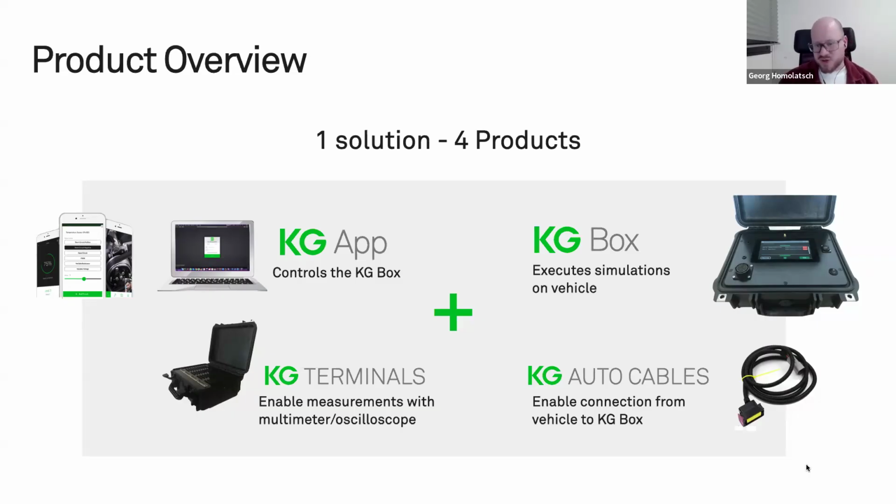That way you don't create any wear and tear on the connectors of the ECU. You can then connect the KG terminals and just do a training on taking measurements, right? Showing students how to properly take measurements with a multimeter, with an oscilloscope, showing students what a healthy signal looks like.